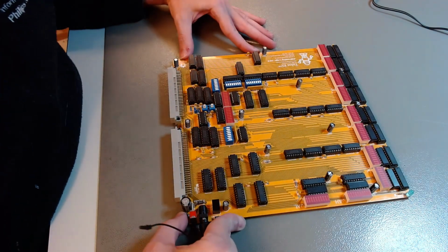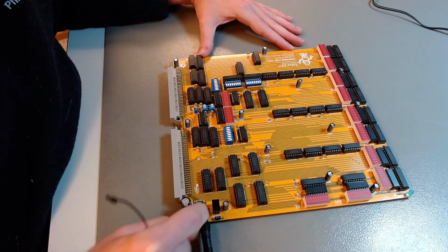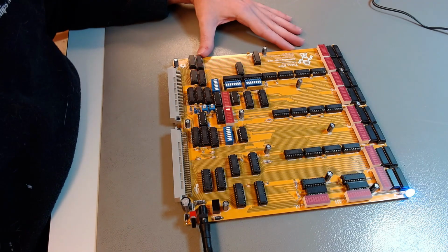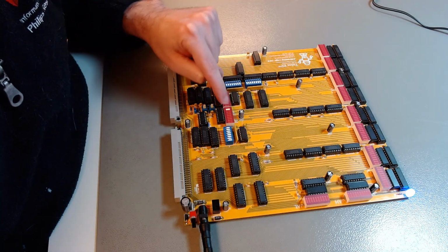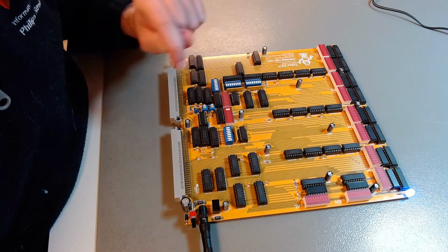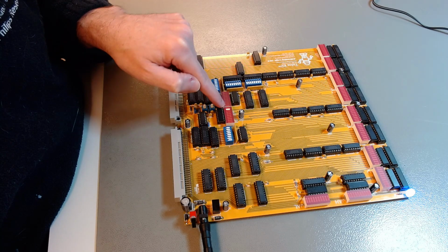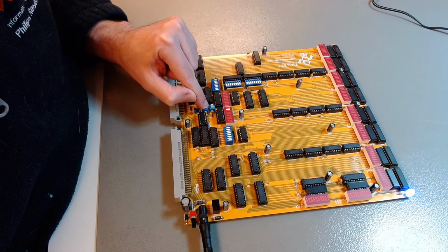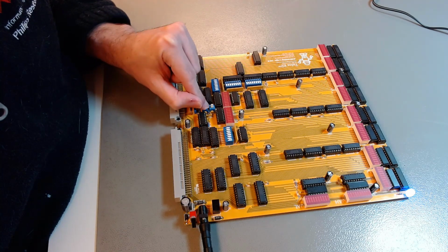All right, let's test the board. I have already connected the 12 volt DC center positive power supply. I just need to turn it on. Let's turn it on now. It is on. There is only one control signal that is active. Well, it's high, and that's reset, but reset is active low, so it's normal to see this one LED shining. If I press reset, it will go low and active, and then it disappears. When I release it, it comes back. So that's normal.